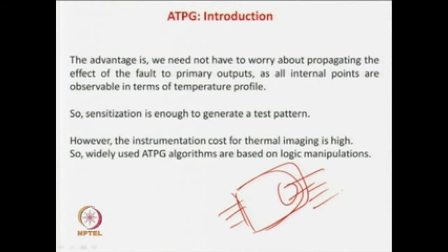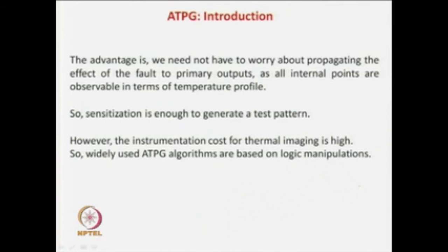But in case of thermal imaging, you give some input patterns, and whatever temperature profile results, you can directly observe with the camera. So, you need not worry about how to generate a test pattern or how to propagate it to the output. Those problems are not there. But what is the disadvantage? Again, the disadvantage is the time required, and the equipment required is very expensive.